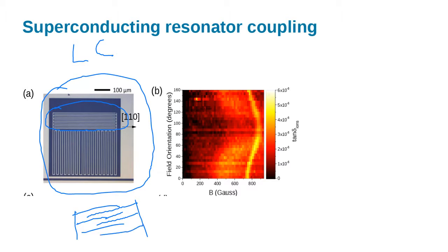So this is our capacitor. If you want to pattern a capacitor on a flat surface, that's the pattern that you make, and that has some capacitance, right? These are the plates here that can build up charge. But if we have interlocking fingers like this, it's like having lots and lots of plates in a capacitor. And this part is the inductor.